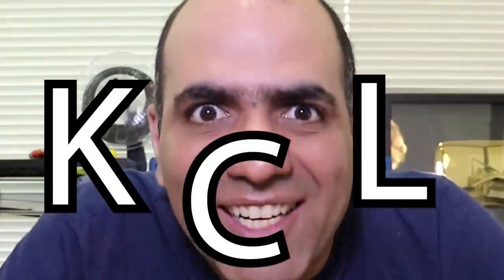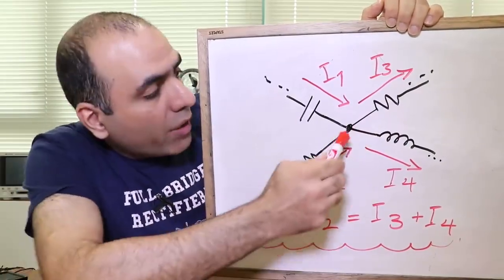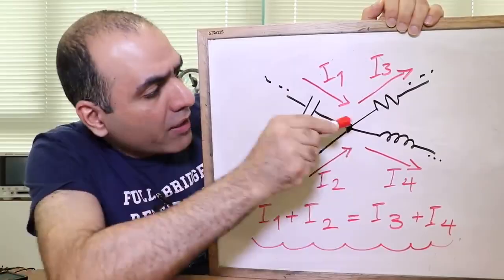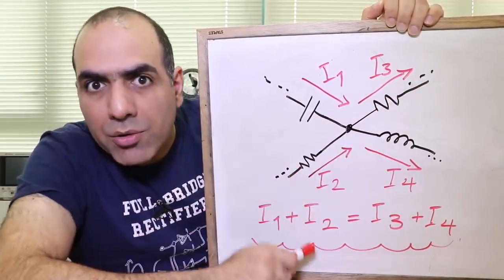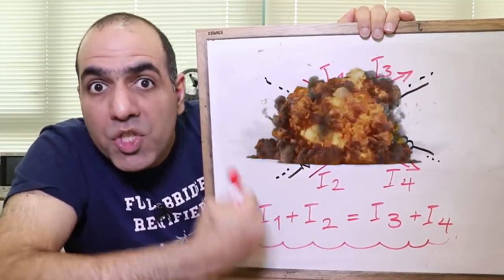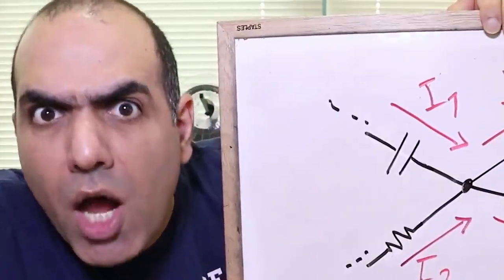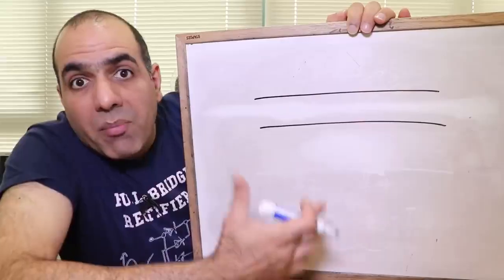But those equations are often not enough to solve the voltage and current values. And that's when you need KCL. According to KCL, if you have a bunch of circuit branches connecting in one node, the sum of all currents going into the node is equal to the sum of all currents going out. Otherwise, it would mean the charges are accumulating in the node, which is impossible. Minding the lumped model again. Stay tuned for more clarification. It makes sense, doesn't it?